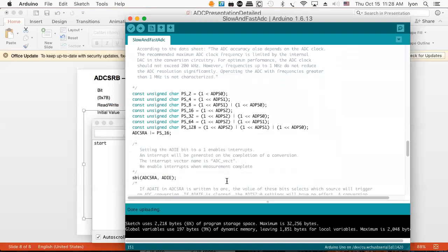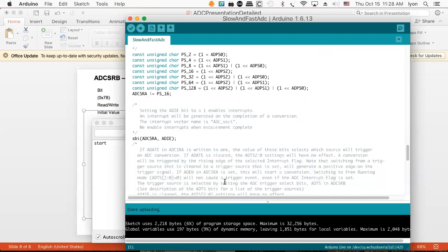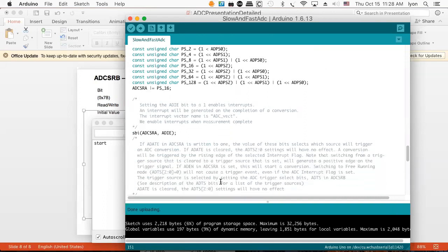So that's actually pretty good for me. And it shows you the trade-off, right? Because if you wanted to go to, let's say, 4 ADC converters, you'd have to take that 76 kilohertz and divide it by 4, because they'd each get the same rate of sampling. So that's a trade-off.